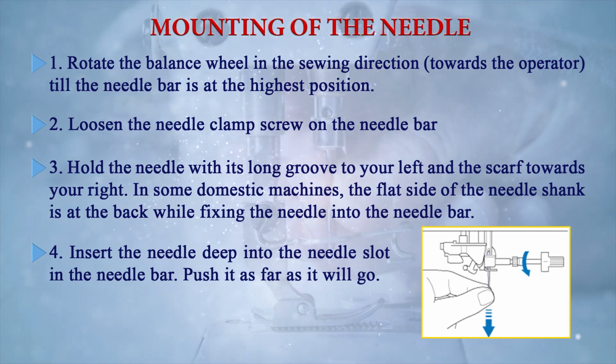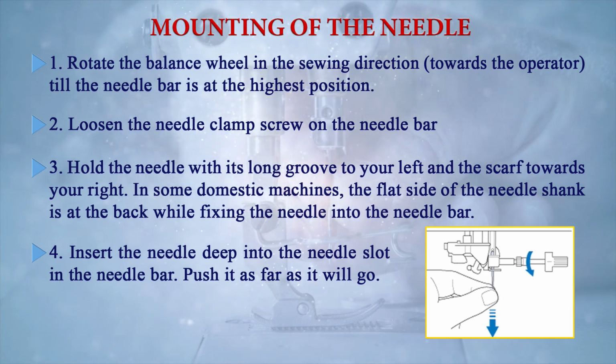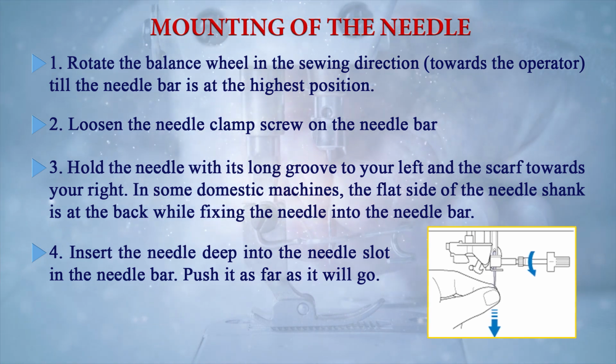So when you put it in the needle bar, just push it upside till it goes and then tighten the needle clamp screw. So this is the process how we insert the needle in the needle bar. Then we have inserted the needle.